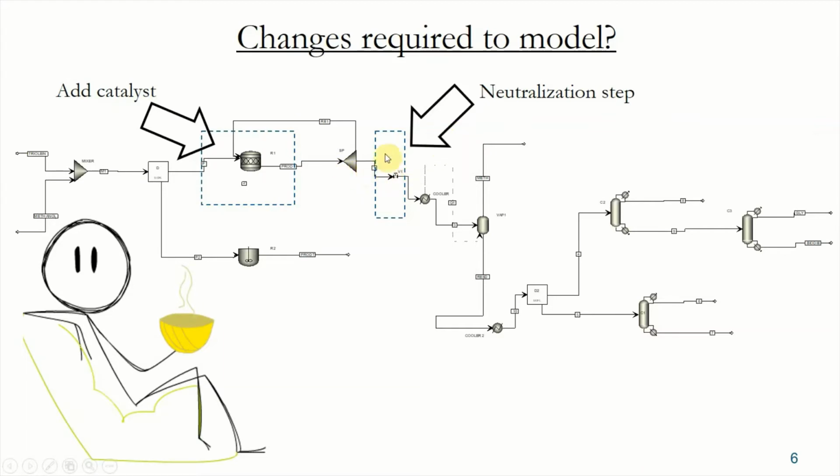To neutralize the acids, right? To form a metallic salt. Now, of course, you also need to introduce a separation step just before the purification steps involving the removal of methanol and the rest, right? So the purification step will involve the separation of the gypsum from the mix. In other words, the calcium sulfate, right, from the mix.